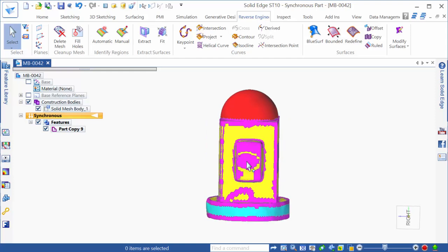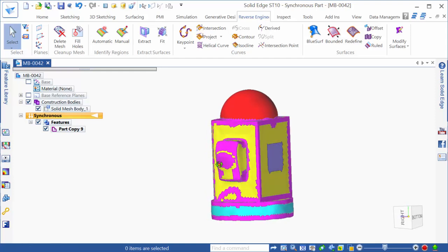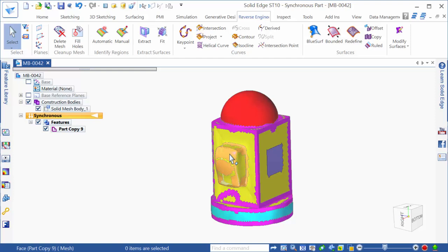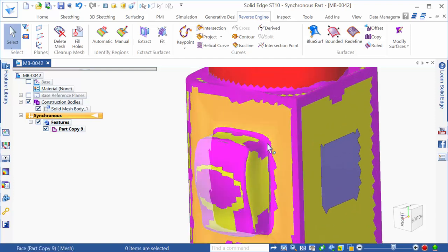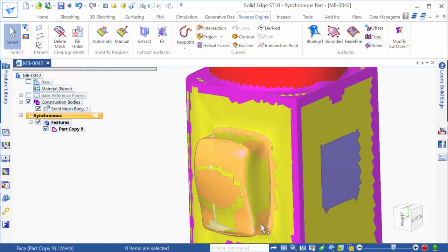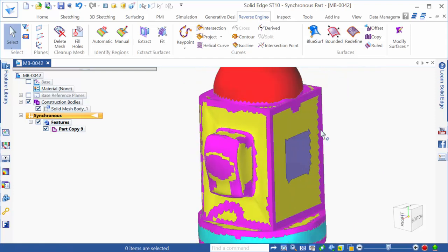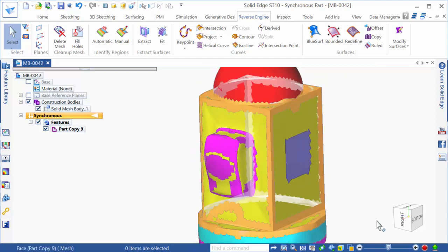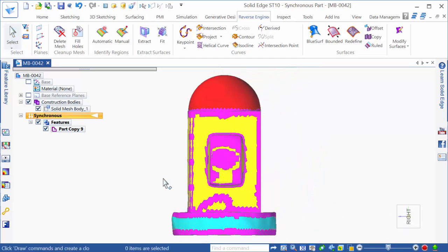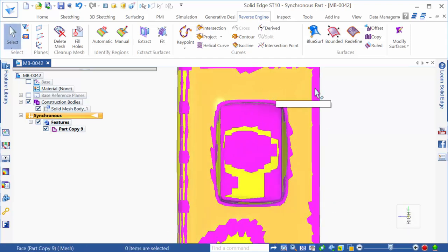But we need to make some changes to this front face here because it's picking up a B-spline, but as I told you earlier, it's where all of the extents of that B-spline go, and we don't want to have a surface that tries to accommodate for all of these curves right here. We just want this top face surface. So we need to do some editing on this guy right here. And that'll make more sense in just a minute as well.